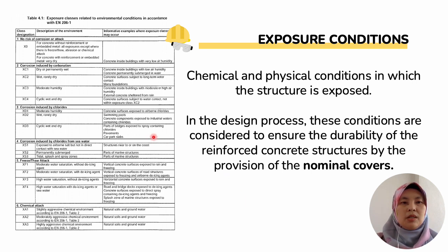Basically, this nominal cover is to protect the steel reinforcements from the environmental effects. So this is table 4.1, which gives us the exposure classes in relation to the environmental conditions.